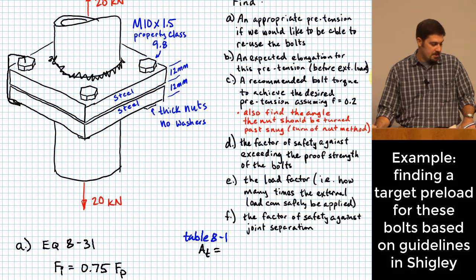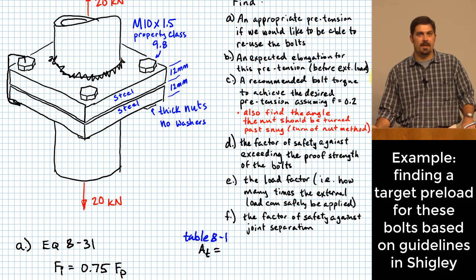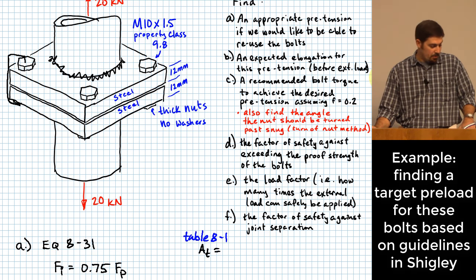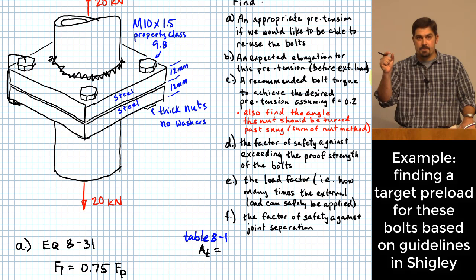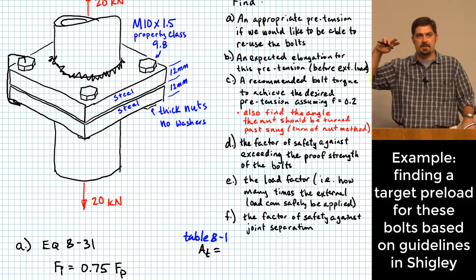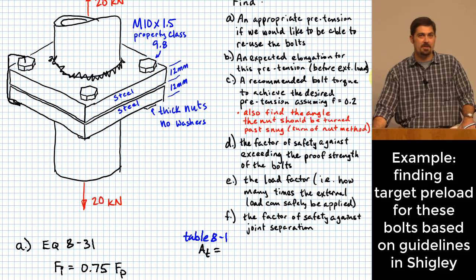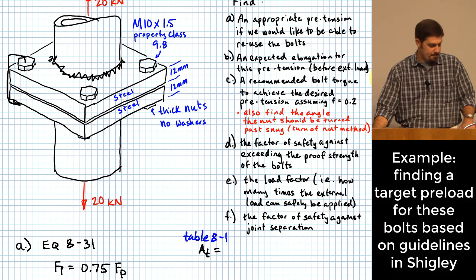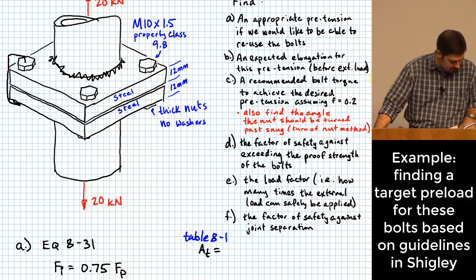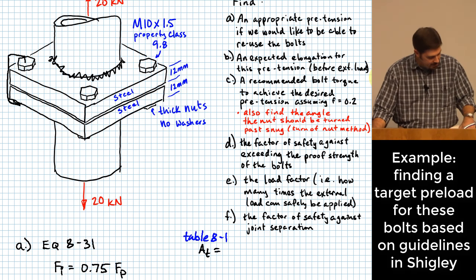In the metric system, what they use is they say, how big is each thread? All right? And so that's what this number is. It means that each thread is 1.5 millimeters in length. So it's essentially the reciprocal of what you do in the US system. Okay? Because we got to make everything weird. We got to make everything hard, right? So I want to mention that, though, is that that is reversed in the metric system versus the US system.